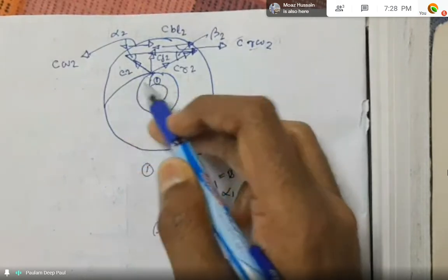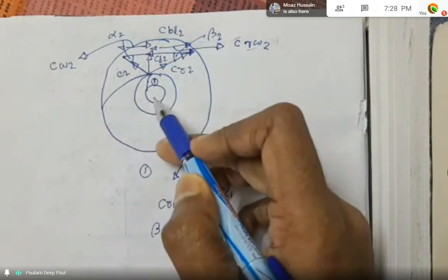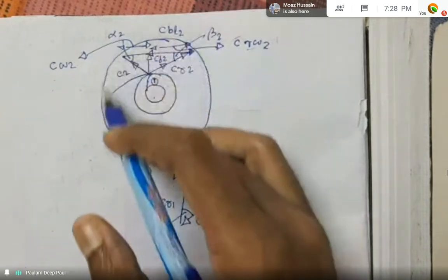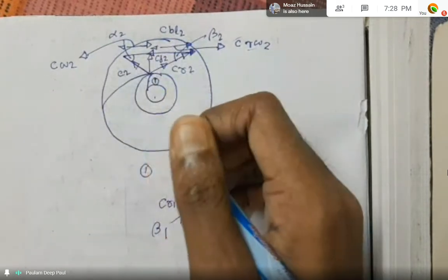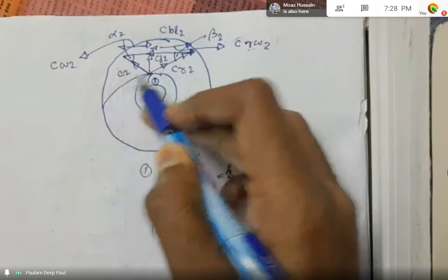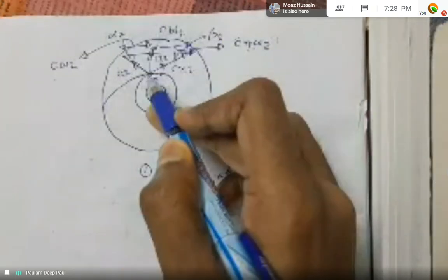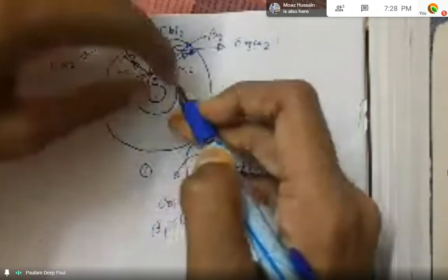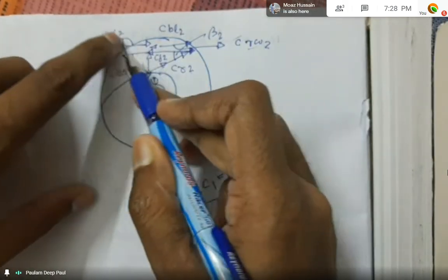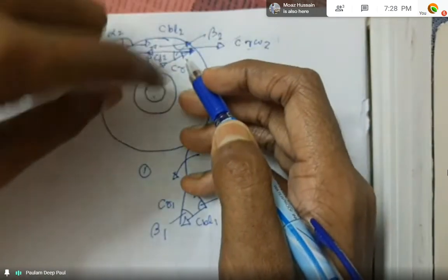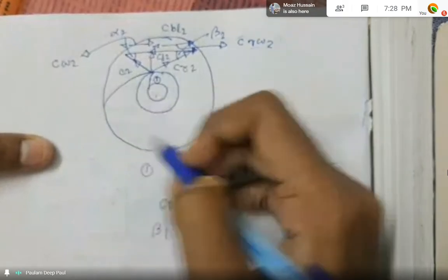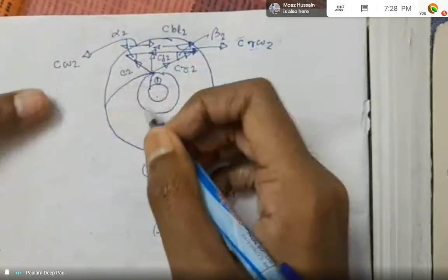That is the radially curved vanes, an impeller here, the radially curved vanes, the impeller. We get a casing, and we get a diffuser that is housed in the radial portion of this casing, like this, because these vanes are coming like this. So as the fluid or the air is moving from the inlet to the outlet, it's kind of a diffusing passage from the inlet to the outlet, with subsequent vanes placed around the impeller, so we get a diffusing passage.